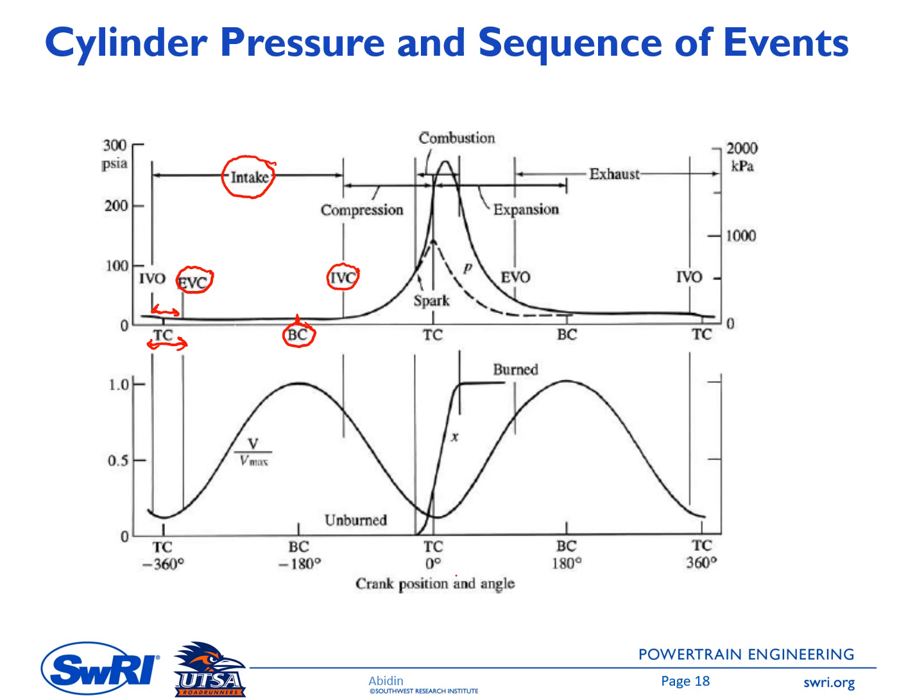Okay, once the intake valve closes, we start having a compression process. The piston continues to move toward top dead center, and you can see in here the cylinder pressure increases as well. Then at some point, several degrees before the piston hits top dead center, the spark will ignite or the diesel fuel will be injected. I think this one is a characteristic of the spark ignition engine. Okay, so this is the spark ignition engine.